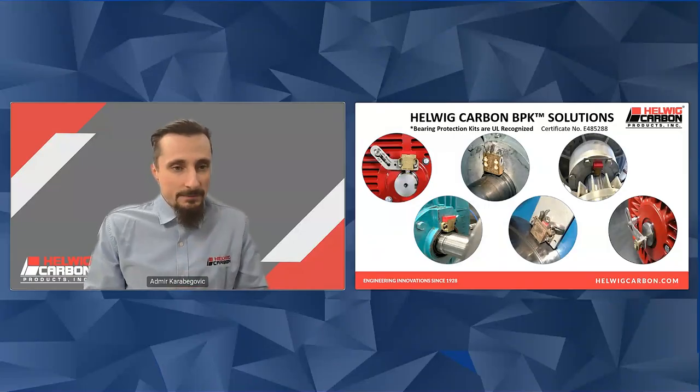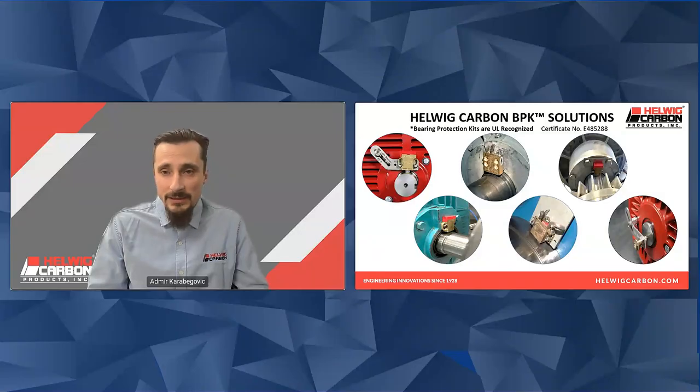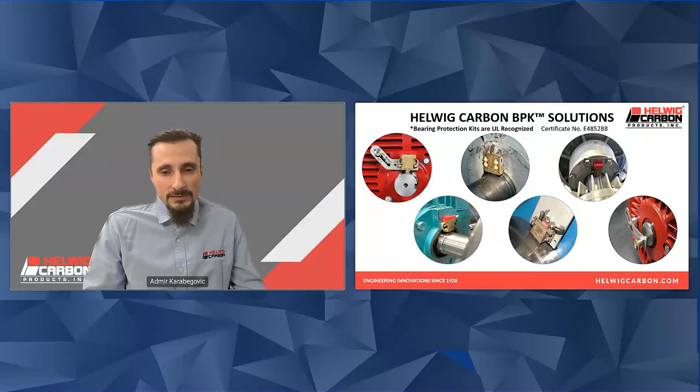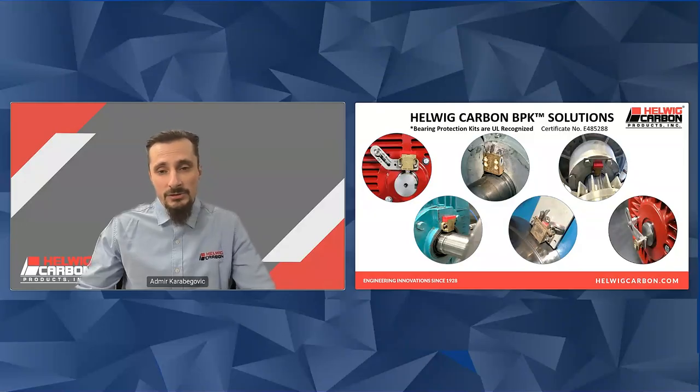In the other kits, some are open concept, and other ones with the red tabs are closed. Those are good for use in contaminated environments. If you have a lot of oil contamination or things like that, that red top doesn't allow anything to be introduced into the kit itself that could seize the brush or cause issues with the spring. These kits are installed outside of the motor, and some motor manufacturers also install them on the inside of the motor as well.